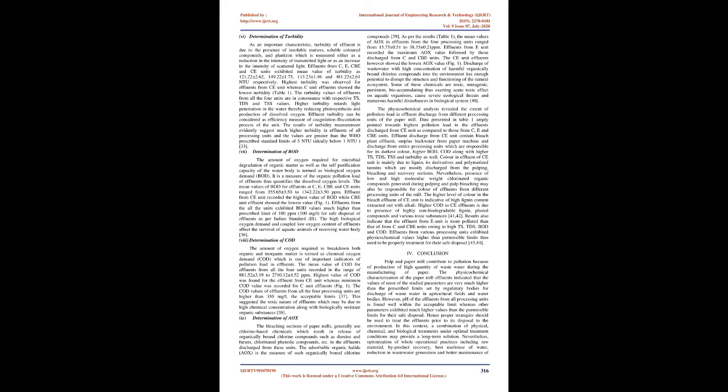The observed values of TDS after the factory effluent discharge were higher than the WHO maximum permissible limit of 500 ppm for disposal into surface water bodies. Disposal of wastewater with high TS in water bodies may adversely affect the aquatic flora by delaying their photosynthetic process due to lesser clarity and consequent reduction in the passage of light.